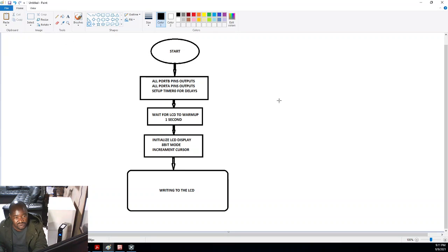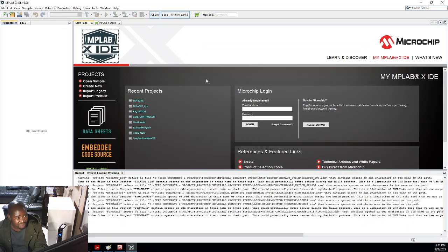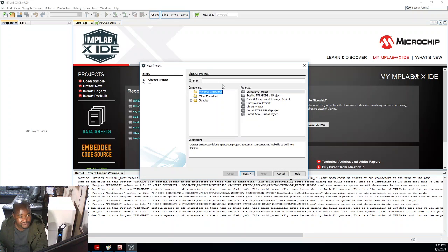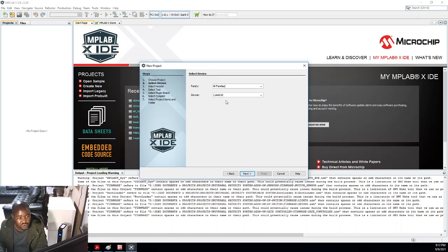Right now, let's go to our MPLAB. For this video, I'll be using MPLAB X or MPLAB 10. And then we will create our project. Go to File, New Project. A standalone Microchip embedded project. Next. Now you choose a device here. I'm going to type PIC 16F84A, or even the 84 is fine.